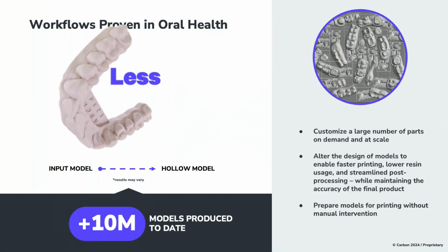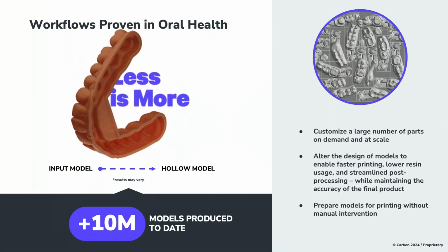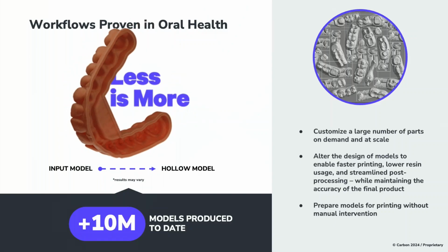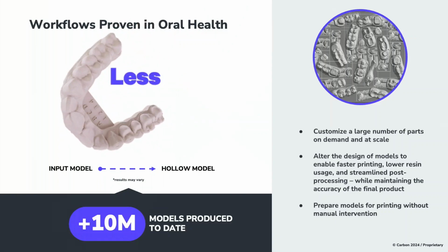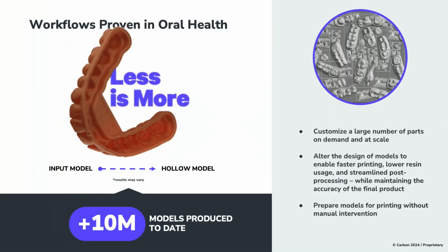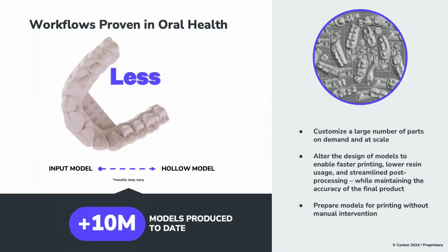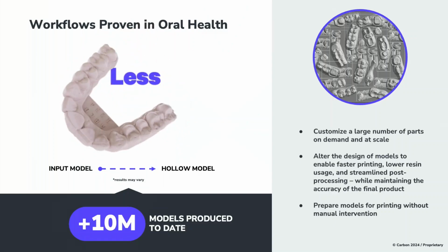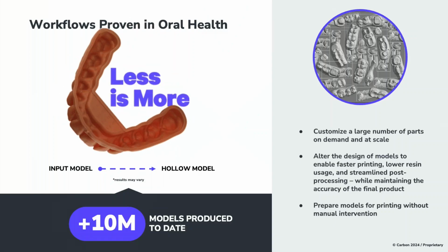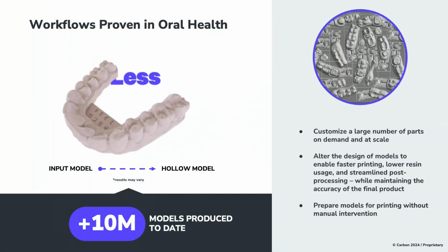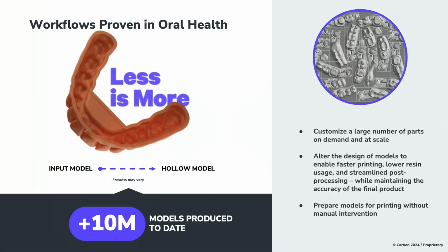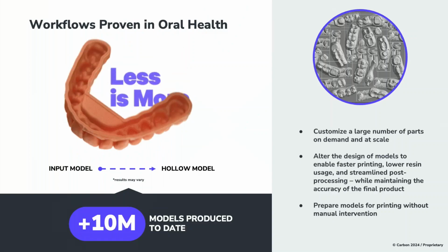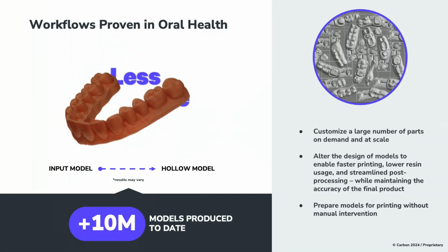We hollow them through a fully automated GPU pipeline, extremely robust, and not only does it just hollow, it also adds vent paths. We can tailor the manufacturability specifically for Carbon processes. Specifically, we have to add resin drain paths so that it can spin properly. So up to this year so far, we've processed through our Hollow Model V2 platform 760,000 parts. And later this summer, we're aiming to be processing 1 million to 1.2 million parts per month.